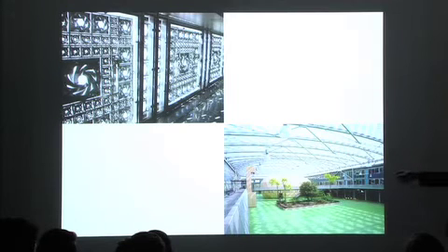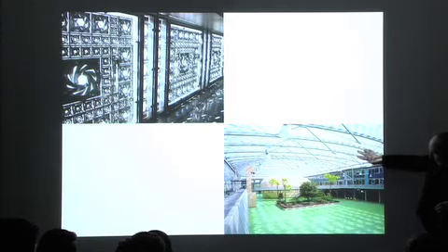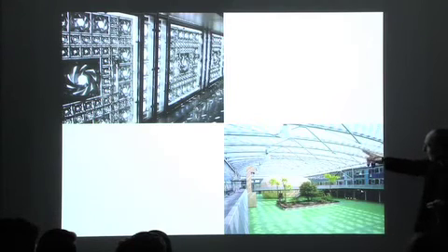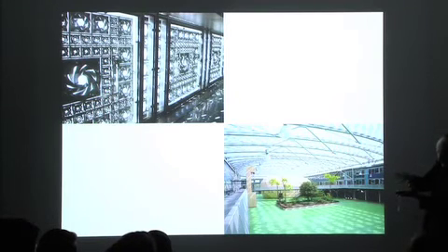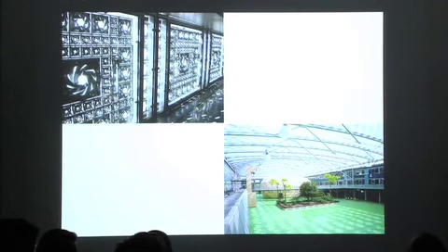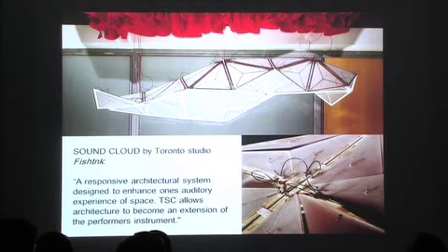This is a school in South London with an ETFE roof consisting of three layers of ETFE, which when it senses too much sunlight, the layers, which have alternate checkerboard patterns, take air out because these are inflated panels. They come closer together, and they darken the space. So they shade the space according to their reading of how much sun is entering the building. So it's a sort of quite intelligent self-shading system.